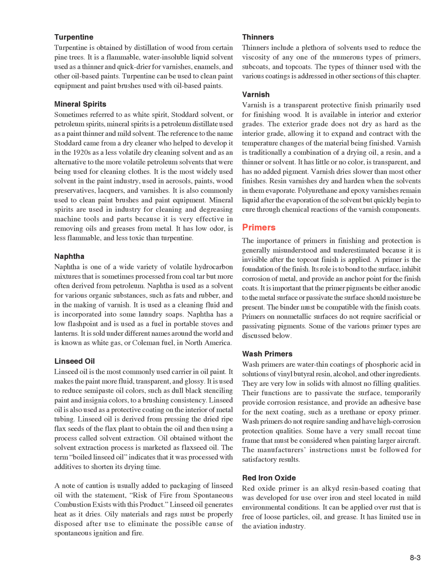A note of caution is usually added to packaging of linseed oil with the statement, "Risk of fire from spontaneous combustion exists with this product." Linseed oil generates heat as it dries. Oily materials and rags must be properly disposed after use to eliminate the possible cause of spontaneous ignition and fire.